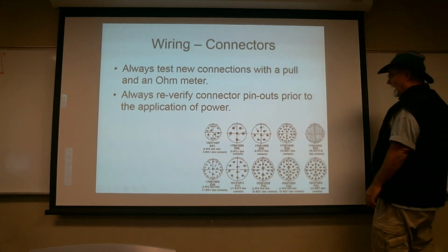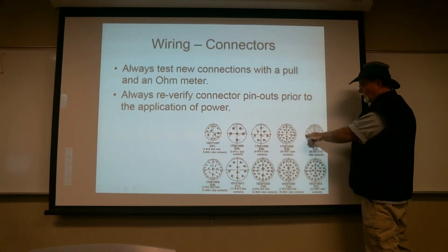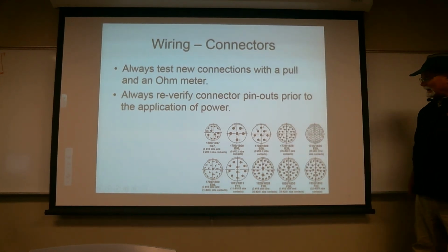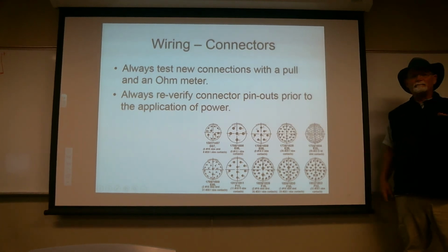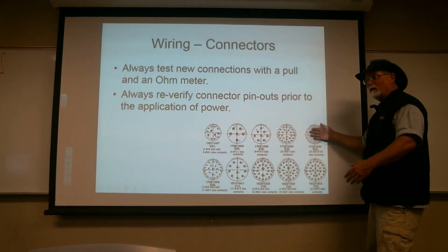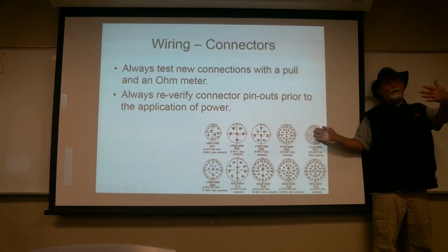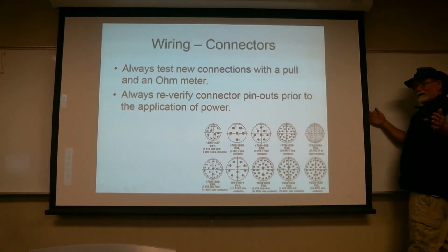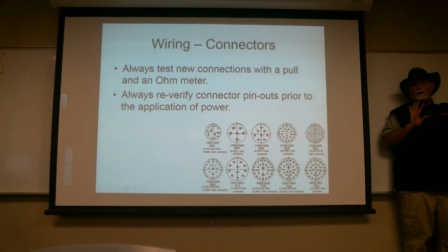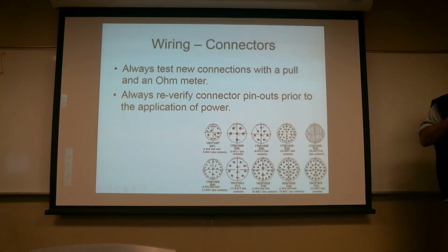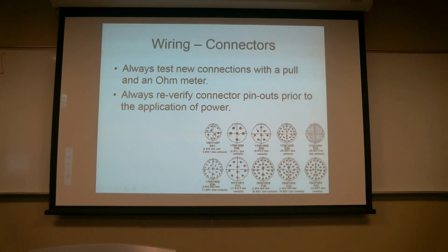Of course, what you're looking at, for some bizarre reason, it says 2 here and 3 there, but 1 is way over here. They do strange stuff like that. Here's the problem. This is the back of the connector. When you come around to the other side of the connector, everything just mirrored on you. Then when you go to the female of the other connector, it mirrored back the other direction. And when you go to the back of it, it mirrored. Okay? See how it can be really easy to get lost. Very, very easy to get lost on this.